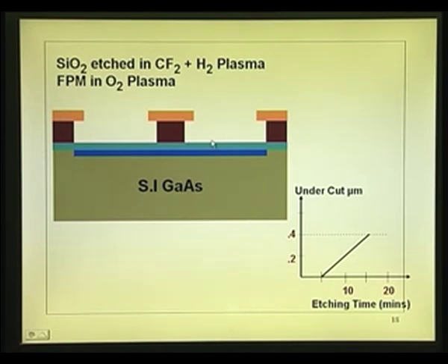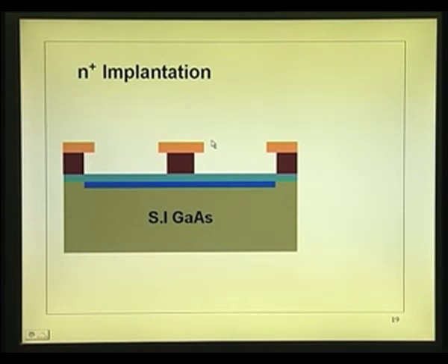Now, go back to this curve, it is very helpful. This is the one through which you implant here with the metal. But in this particular case, what you are doing is you implant using this mask. See the implantation coming through. So, wherever silicon dioxide is there, implantation does not take place. That is N plus. So, this is the channel which has a low dose of 10 to the power 11 or 10 to the power 12. This is 10 to the power 13 per centimeter square dose, very heavy dose at 200 keV, so that you can go deeper. Then I got now a channel region. If I can put the metal here, there is a gap this much, which corresponds to this undercut. That undercut can be precisely controlled by etching time.